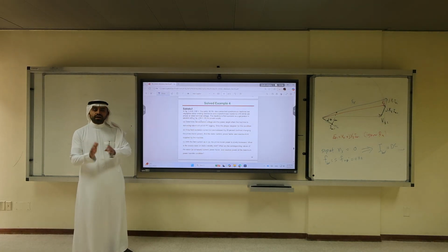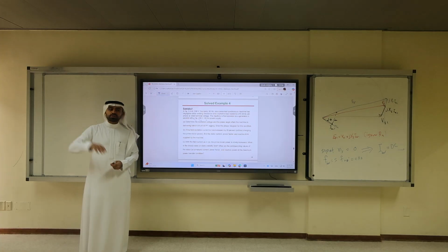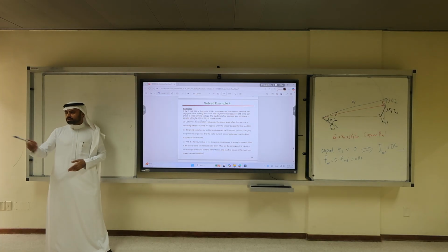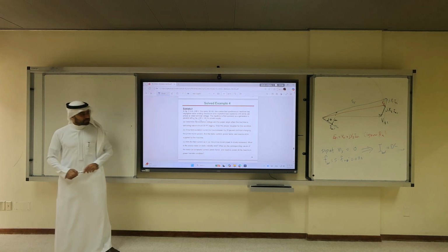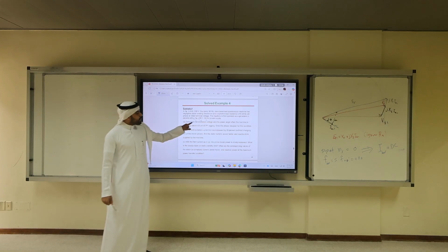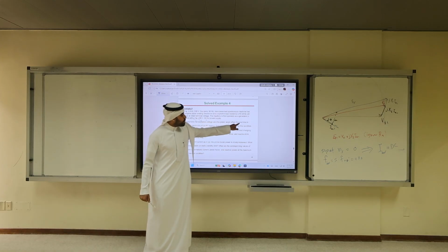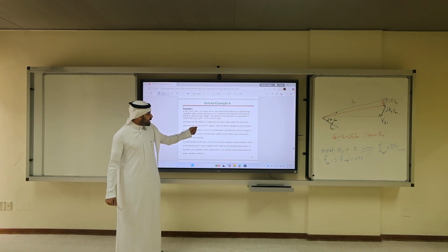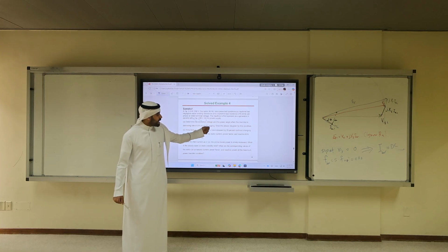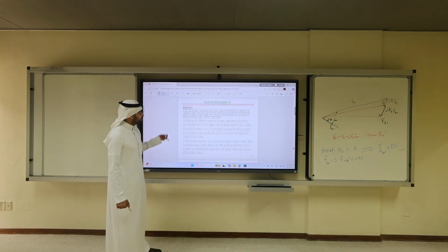So we satisfy the 4 conditions that most of you didn't know in the quiz. And the solution is posted, okay? The solution is posted. And yes, generator B was leading. Find the excitation voltage and the power angle when the machine is delivering rated kVA, it means rated 5 kVA at 0.8 power factor lagging. Draw phasor diagrams for this condition.